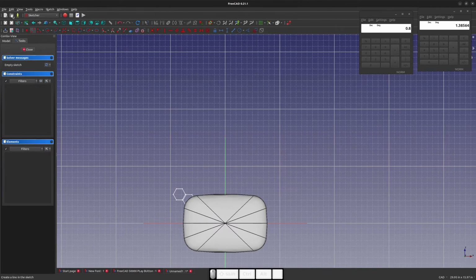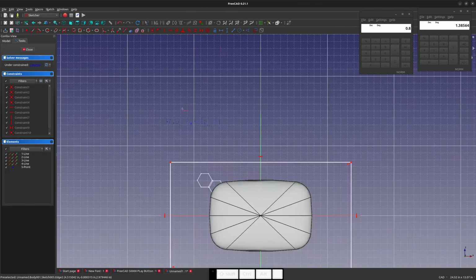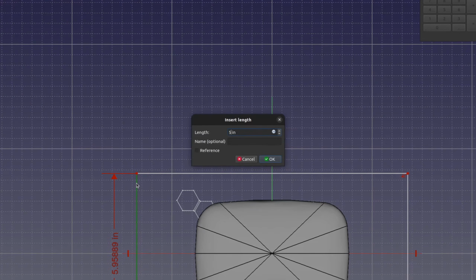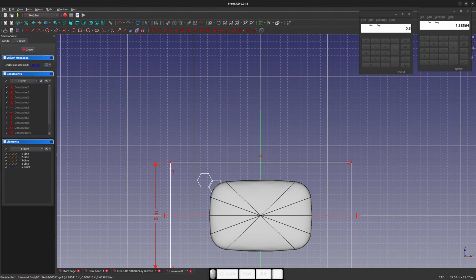And on this sketch, we'll choose this plane. Change back to driven dimensions. I'll go with the center rectangle. And again, I just look at the constraints and I can tell where I'm on the origin. So we're going to go right there. Now I can fully constrain this if I want. That's certainly best practice. We'll say 6 inches.